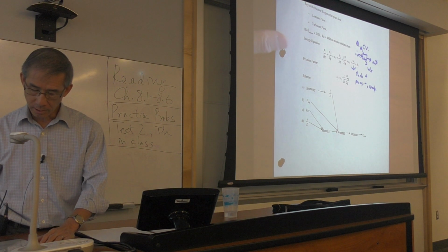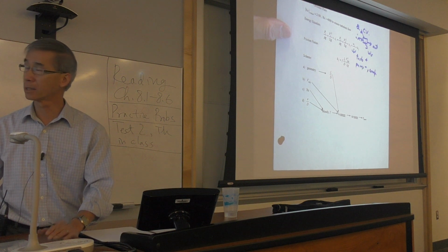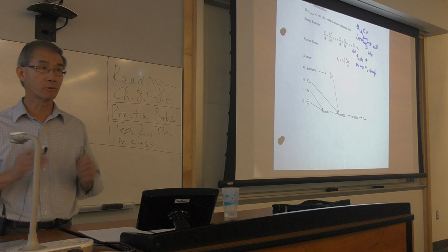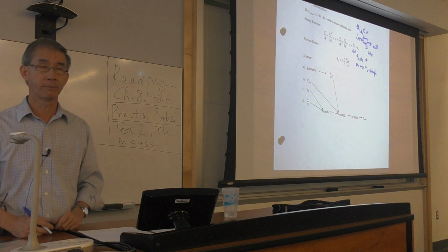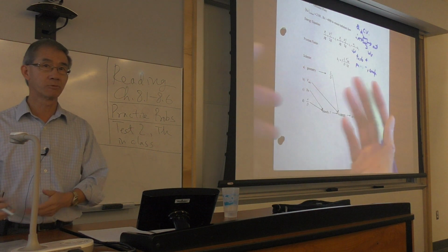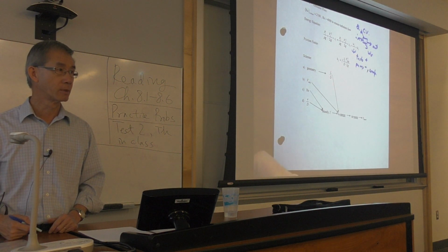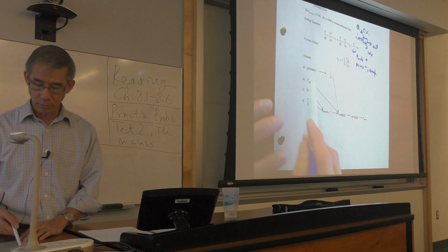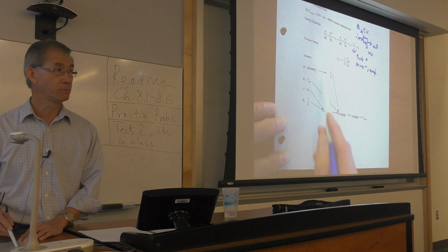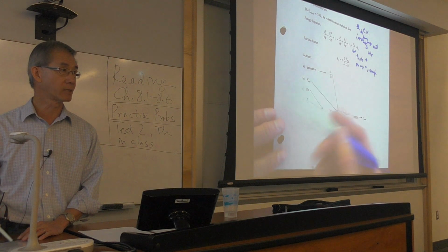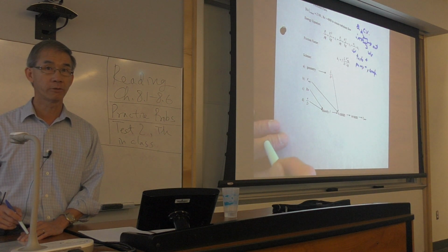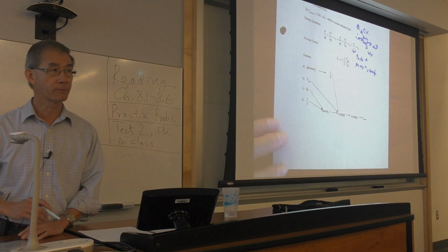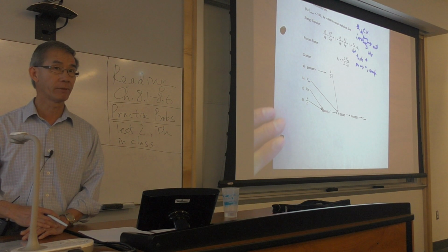Okay, the rest is really the key point is the energy equation and the good grip of it. The rest is just bookkeeping. Thanks to Mr. Moody, you know how to read the chart. And then you know how to use that to go this route, which is give me a flow system, geometry, length, etc. Give me a flow rate, Q, and I will tell you what pumping power I need, no matter how complex the system is.